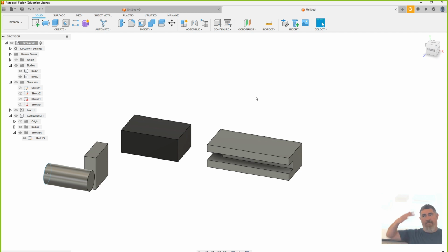And so just have your little checklist. I should actually make that into a checklist for you guys, huh? So I'll make it into a checklist for you guys of the things to think about when you open a model. I'll work on that for you. But keep that in your mental checklist: metric, where should my origin be? Am I using patterns? What kind of features do I want? What things might I change and should I make as parameters?